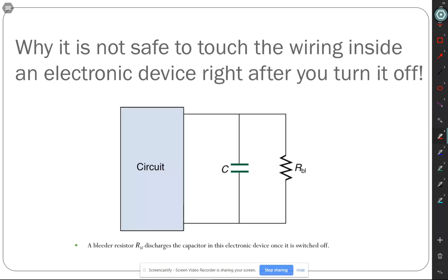If you come out and say, well, let's check it, and you touch it, if it has a high enough voltage that the current through your body is over 10 milliamps, it's probably going to make you jerk like this. And then what happens? You can't let go because your muscle is now contracted. And so you sit there going, that's not good.